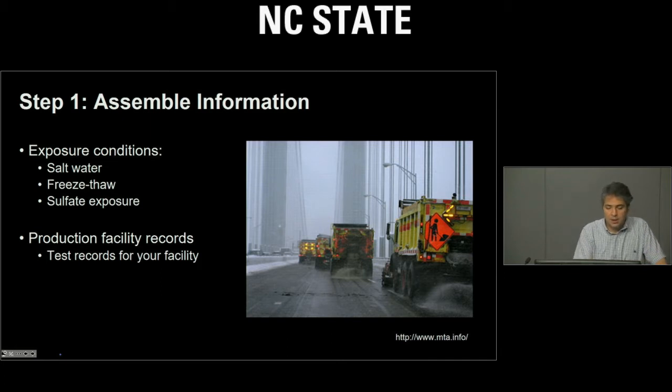Is the concrete exposed to freeze and thaw cycles? Do we have sulfate exposure? For example, if this concrete is placed as a foundation inside the soil, does the soil have excessive amounts of sulfates that might deteriorate the concrete? So we need to assemble all of this information.